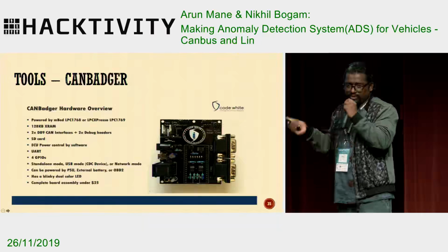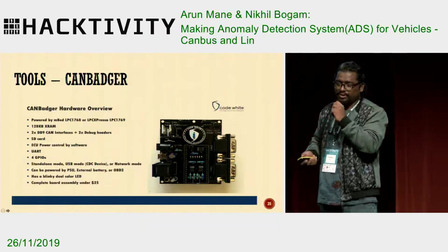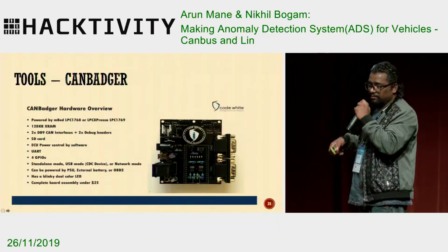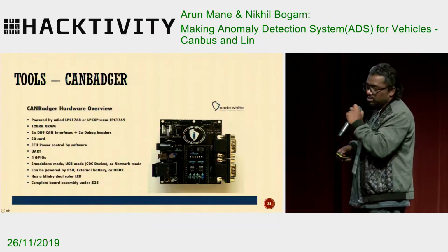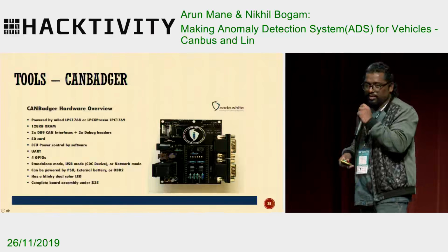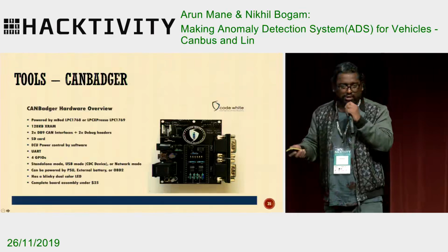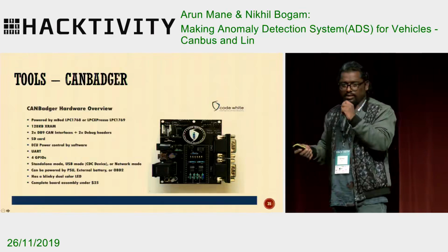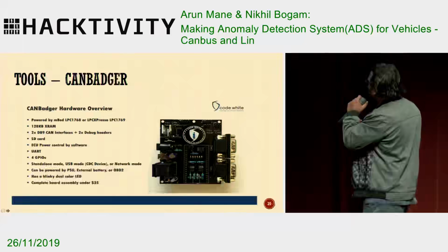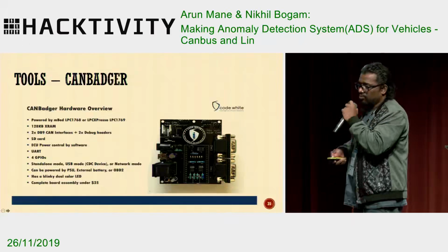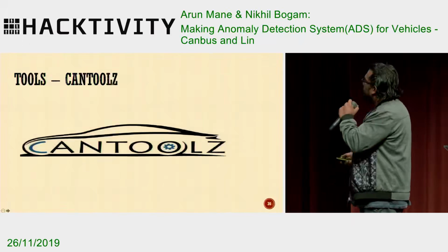So if you take the entire BOM, it will cost around $100, and it's very good for a man-in-the-middle attack on the CAN bus, because it supports 2 DB9 cables. So you need to have the DB9 to OBD2 converter, or rather the cables, and you just attach over here, and you can start intercepting the communication, and you can do a ton of things.